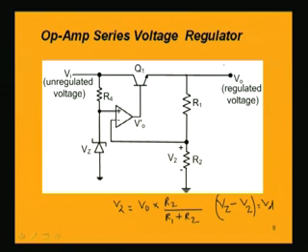So what is happening from the whole analysis, we see that even though V0 is increasing, the regulator circuit is acting in such a way that finally V0 is decreased. That means the resulting outcome is that finally the output voltage V0 is maintained at the constant level.